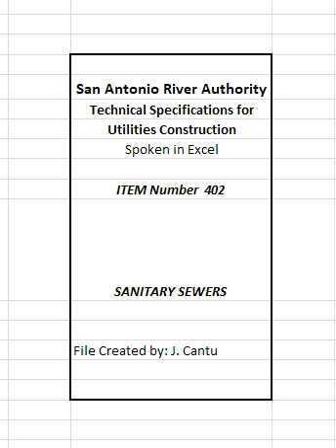The basket or other similar device shall prevent passage to the sanitary sewer system of solids greater than 1/2 inch in diameter. The lint trap size shall be based on the total G.P.M. of all fixtures, appliances, and appurtenances draining to it. In lieu of a lint trap, a lint interceptor may be installed. The interceptor shall be sized and designed by a Texas-registered engineer with his seal and signature on the drawings.